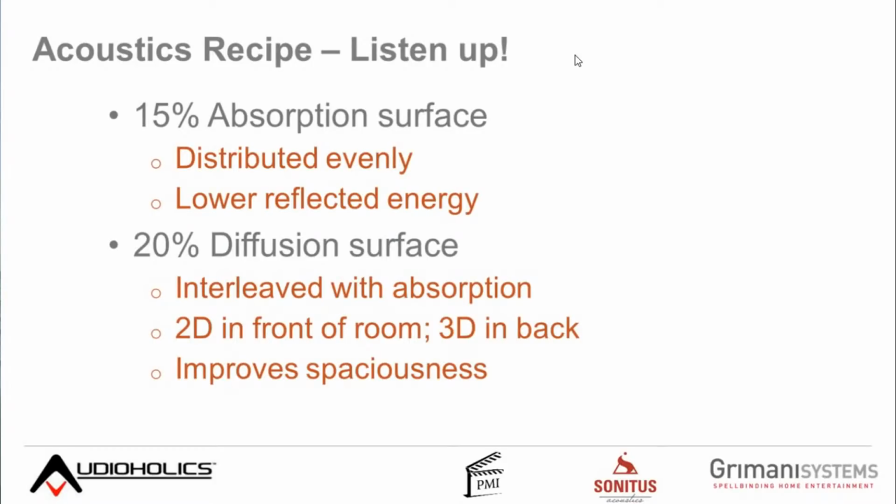I have some diagrams for this, but typically just think of what's going on the wall as essentially covering below your ear, going above your ear with some absorption, and then stopping, because we want to maintain some reflection in the room. I'm going to keep saying that. We want to maintain some reflection in the room. It's a common misnomer from people that the minute I start talking about acoustical treatments, I want to cover all the walls. Nope, that's not going to work.